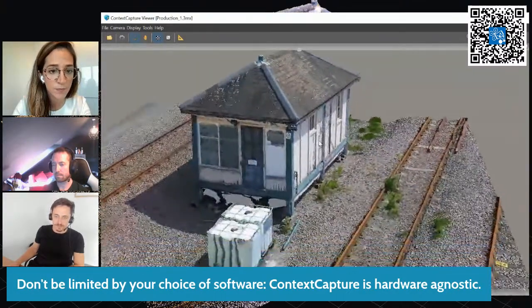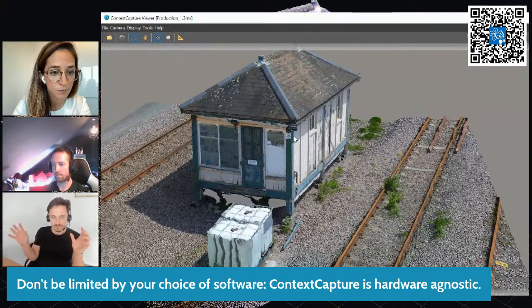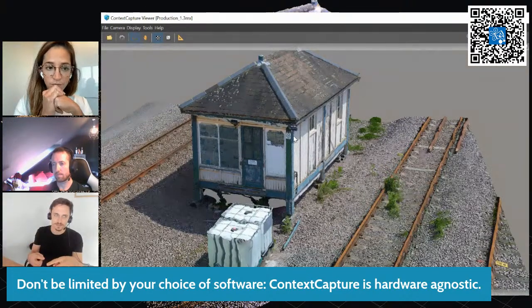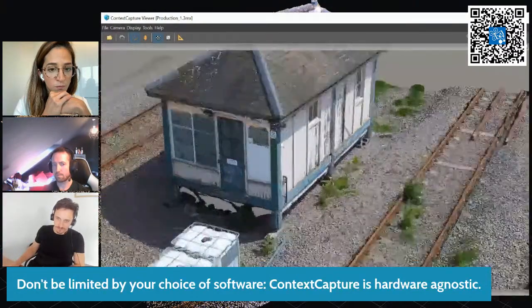Exactly. So what is first of all important, it is not required for you to have the point cloud or photogrammetry covering 100%. If you scan the inside of a building with terrestrial laser scanning, you will create a mesh inside only from the point cloud. If you have only part of the terrain taken with the drone, you'll create a mesh only from the photogrammetry there. The software won't tell you, okay, you decided to go with both, but you are missing information in some part. No, it's creating everything together. So at the end, you're getting results